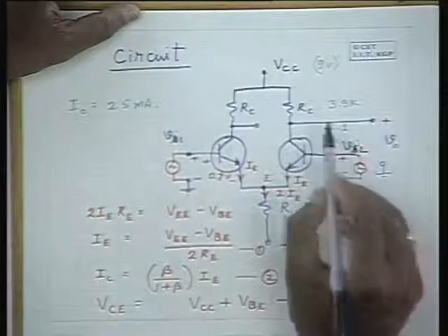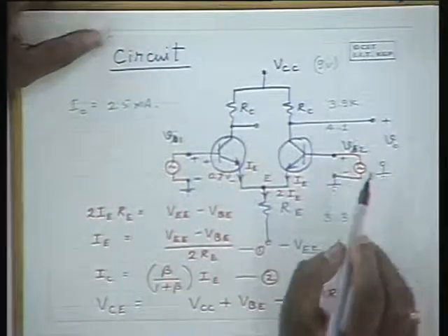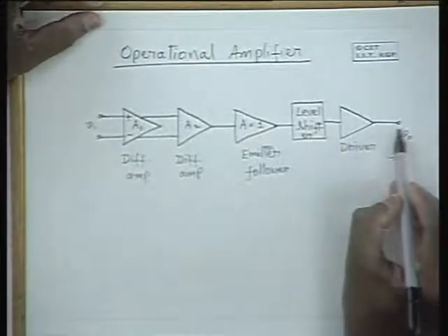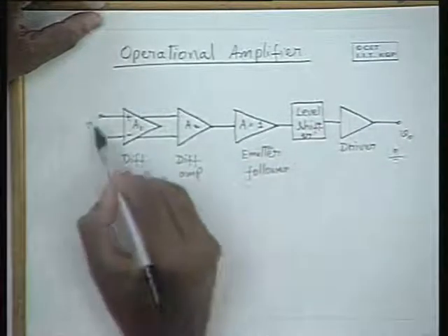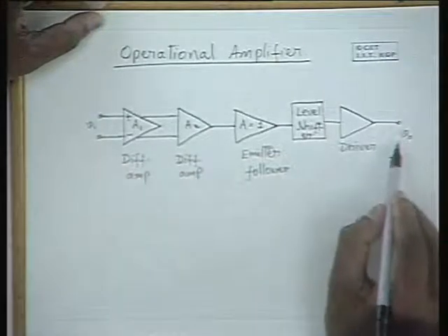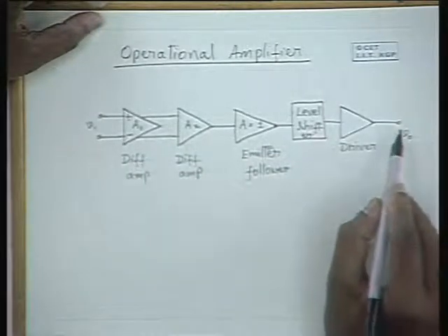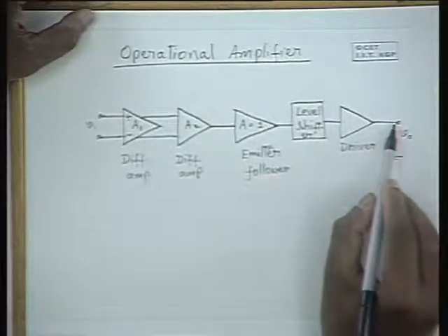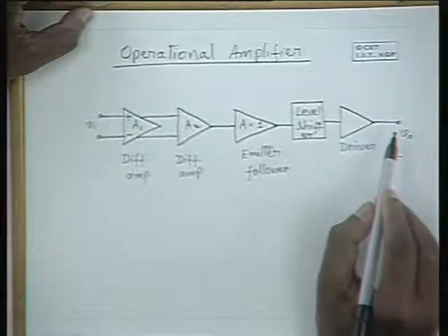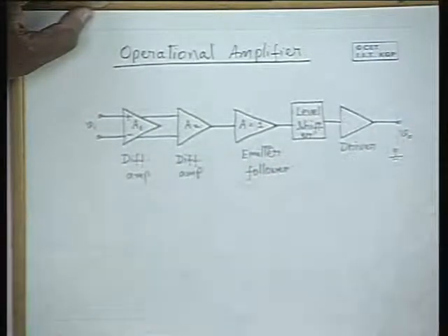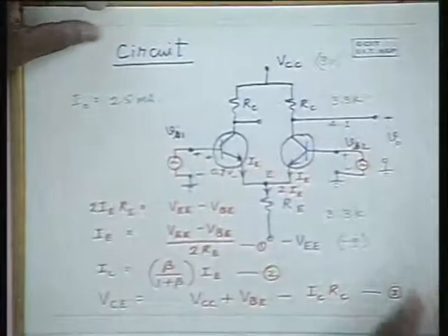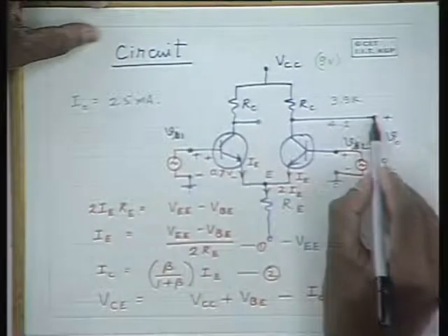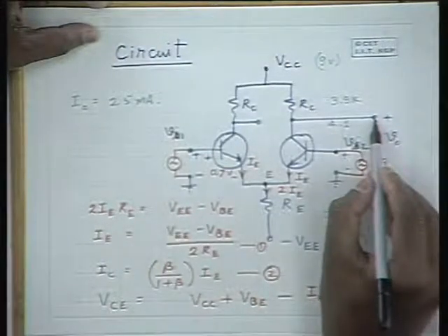But when we take the signal output towards the end of the amplifier, for a 0 DC input, the output voltage should be 0, and that is possible only when the last stage amplifier is biased around 0 potential. So the biasing voltage should be 0.